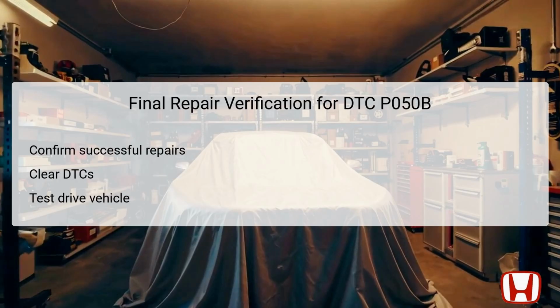After all necessary repairs and replacements have been executed to address the P050B code, it's crucial to conduct a final verification of the repairs. Begin by confirming that all components, including sensors and air intake elements, have been replaced or repaired properly. Once confirmed, clear the DTCs using the Honda Diagnostic System, HDS, to reset the vehicle's onboard computer.